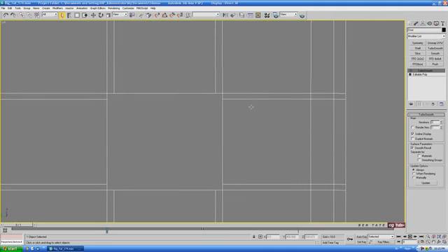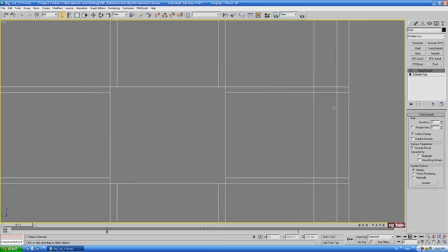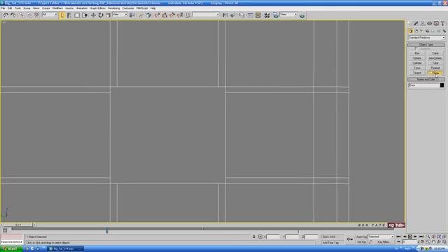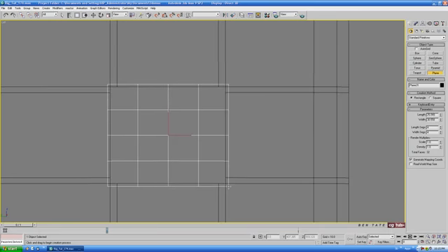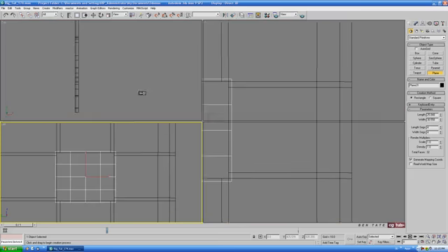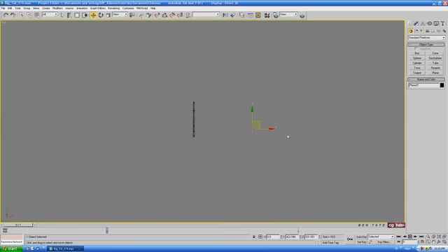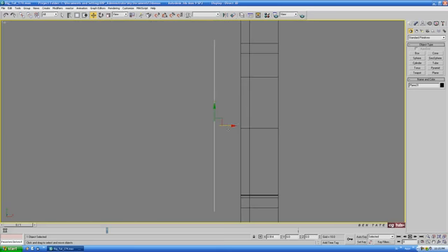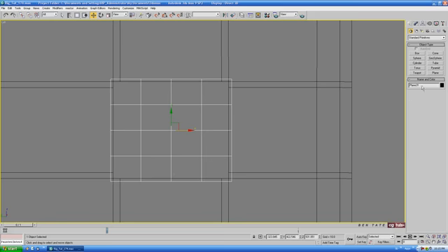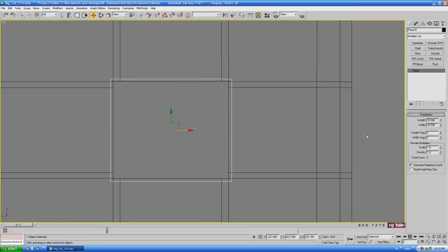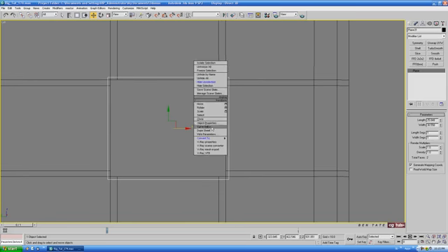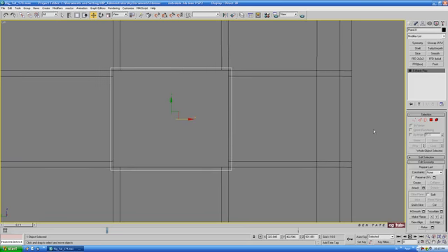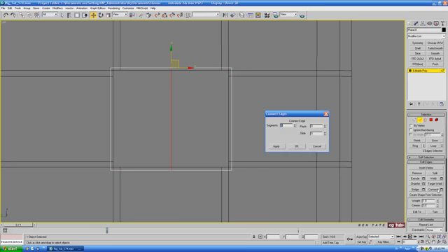And we'll just model the handle out of maybe a plane. Alright, so we'll drag it a little bit bigger than the hole again. And let's move it forward. So let's push that out in front slightly. And we can also get rid of these segments each way. Alright, so we'll come to Editable Poly. And let's maybe give it a few extra edges here. It's going to grab the top and bottom there, do a connect. Let's do 2, and we'll just slide that out.